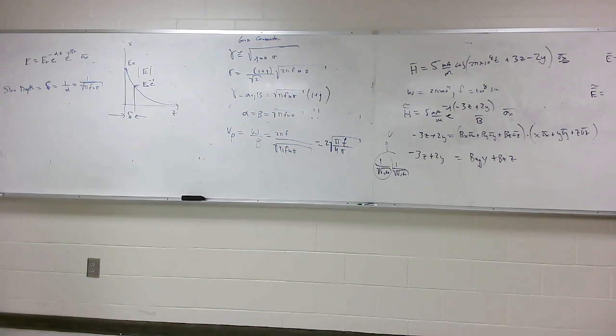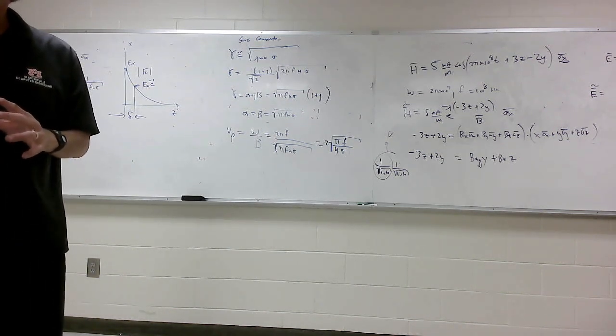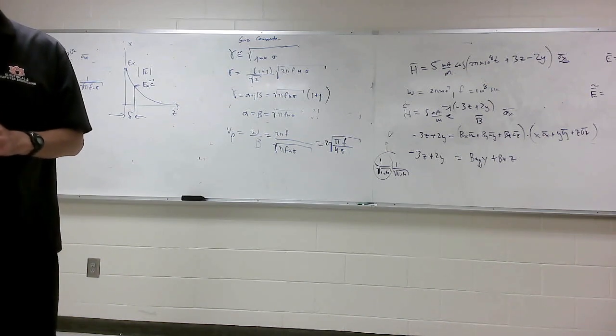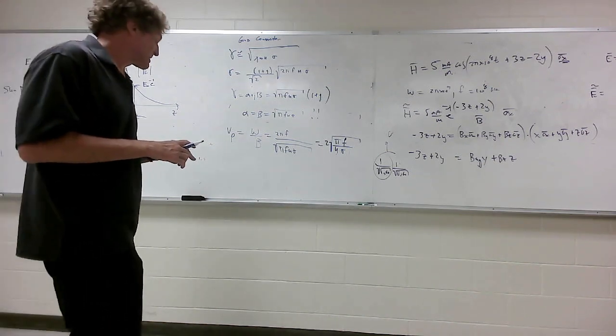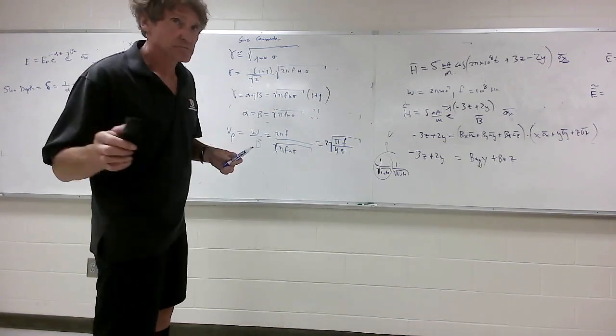That's the skin depth. So what does that mean in terms of something practical? Well, it means for wires, we can calculate the resistance of wires, the AC resistance of wires at any given frequency. And it'll change because of the skin depth. Let me try to make sure I say this part, because this is important.